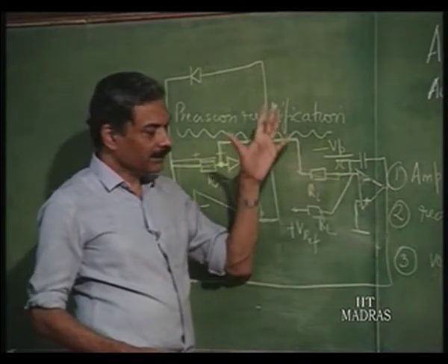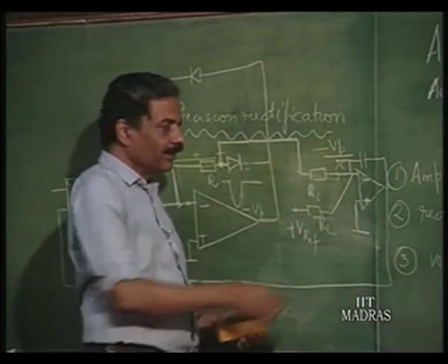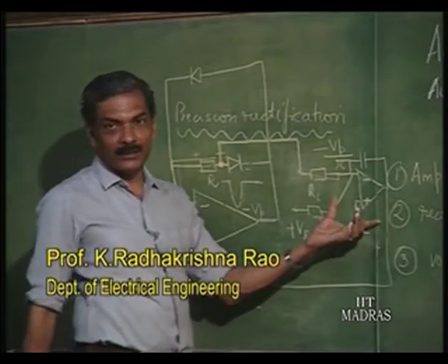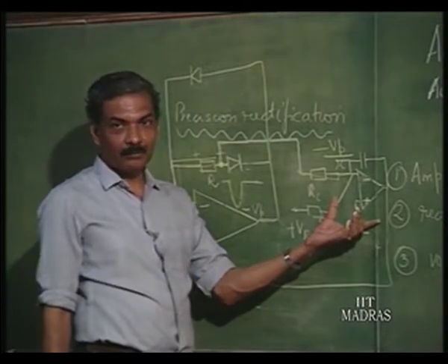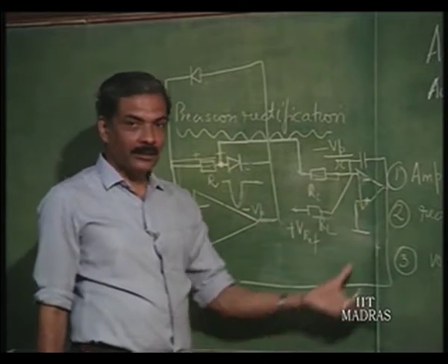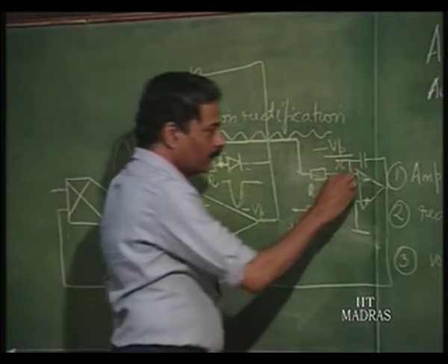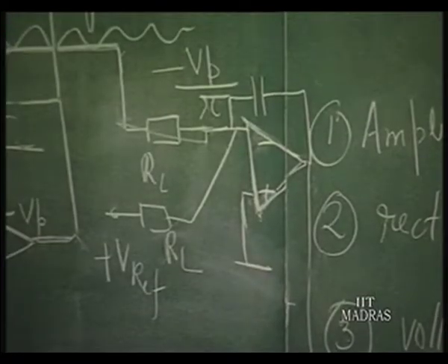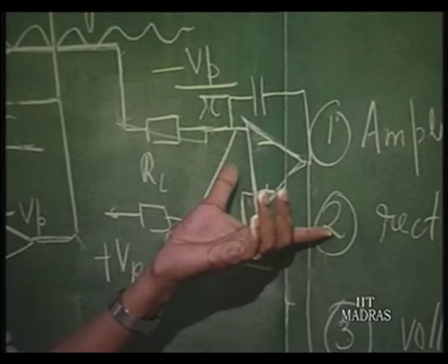Okay. Both of these things work satisfactorily without any problem, but it is more common to use this kind of thing. You can see that this uses what is called an integrator here, and this, according to the control system people, is called an integral control system. So, the steady state error is supposed to be 0 in an integral control system, even though it is very slow. Okay. It is a slow control system, but steady state error is 0.